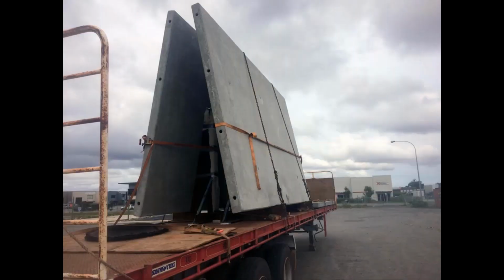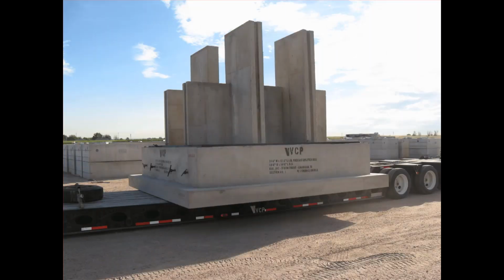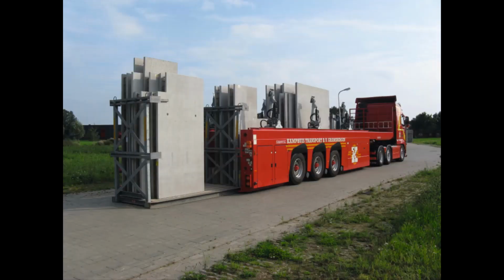Standard flatbed trucks can carry panels up to 40 feet long with a total cargo weight limit of 40,000 pounds. For example, a standard truck could carry 2 panels with a unit weight of 75 pounds per square foot and dimensions of 8 feet wide by up to 33 feet long each. There is a major cost advantage to being able to ship 2 panels in one load if feasible.